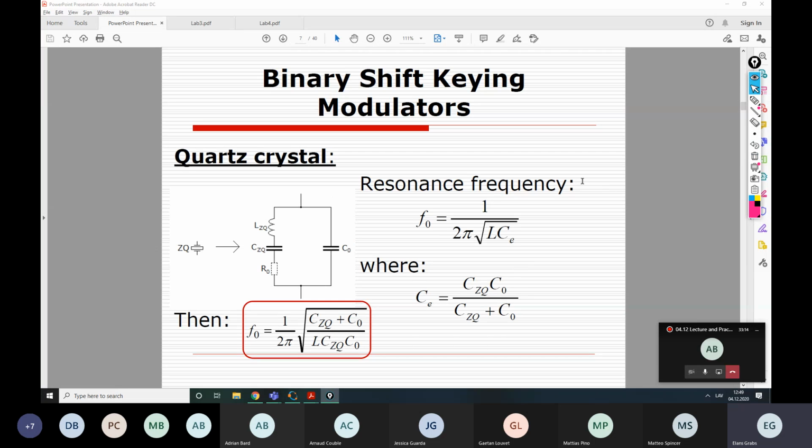Now, for the quartz crystal, however, this piezoelectric effect works as a compensator. So imagine that the temperature changes, so the frequency changes and the voltage changes, and then this change of the voltage tries to reshape the physical form of this quartz crystal, which of course will prevent that and try to keep its own form. It has some inertia. So basically, this resistance to changing the form will put our signal back to the frequency where it should be, right? So this works this way.